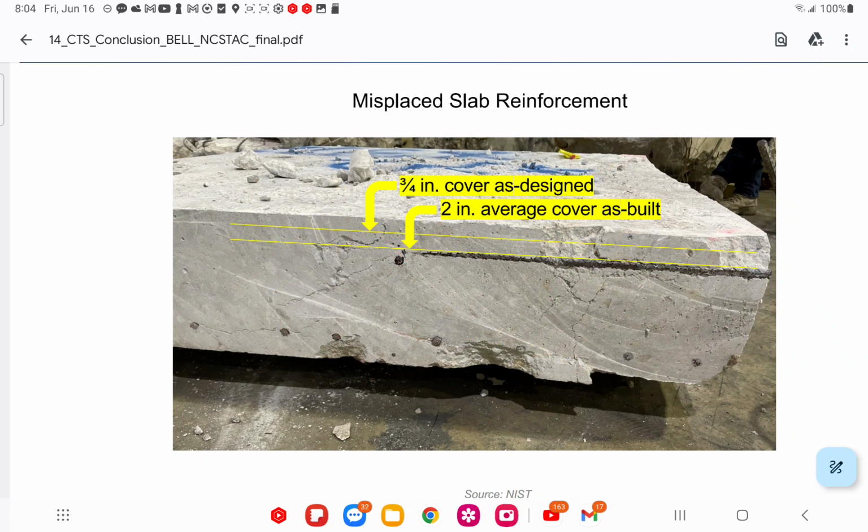I'm going to remove this and you look at it. So this was not an experienced concrete cutter who did this. They were all over the place. In fact, they drifted their machine in, because you can see a shelf made there. That means they moved it, plunged out, then plunged back in, and it creates a shelf. The first one was further out towards us. The second one appears to be inbound even more. Same thing with these. They're in and out, in and out, in and out. So the person that cut this was drifting a lot, in and out, up, down, over.